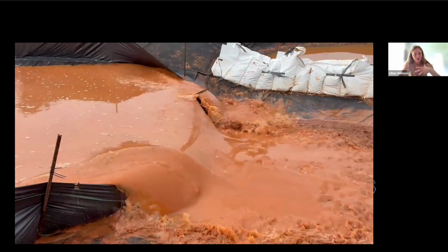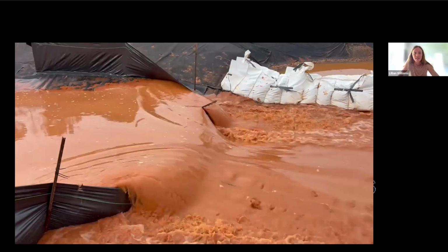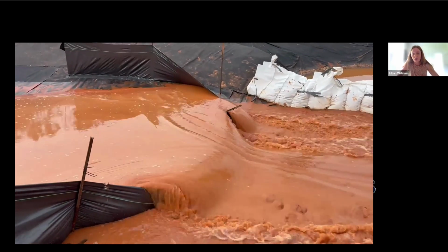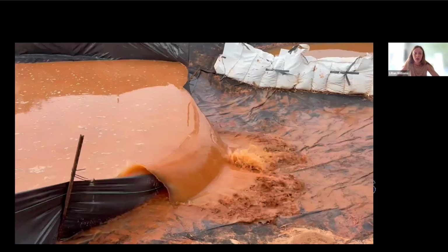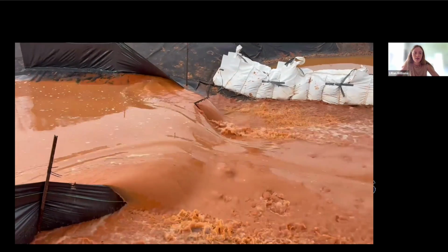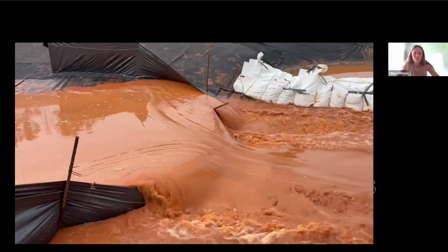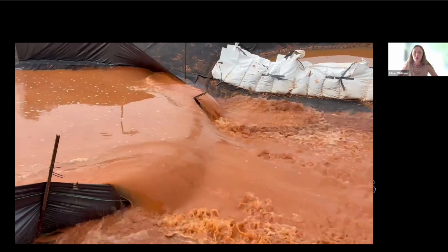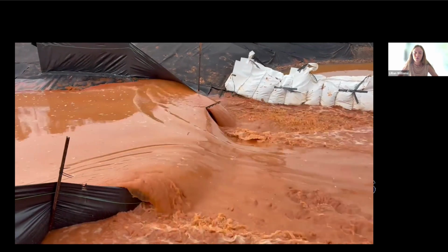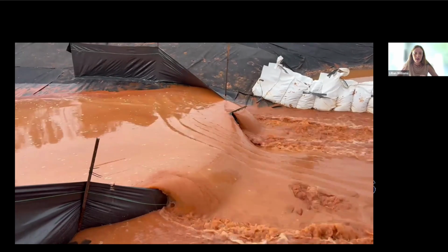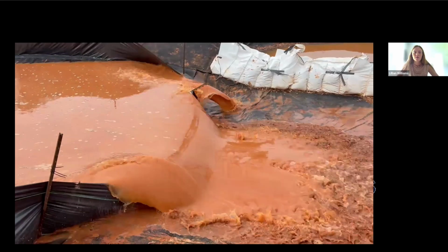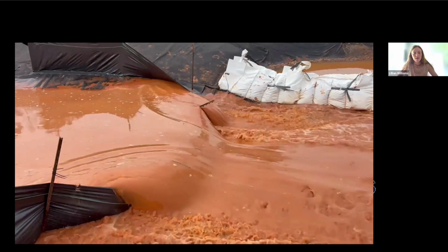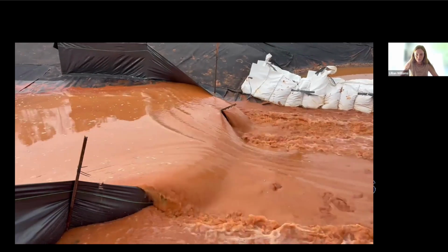And then this is what happened during the test. You can see that 17 minutes into the very first test that we ran, we observed failure. And this is very in line with other research by Brian Roche, that when he studied the low porosity silt fence, actually for Nebraska, there was this kind of failure when a lot of the water built up on the face of it and it couldn't handle the force.